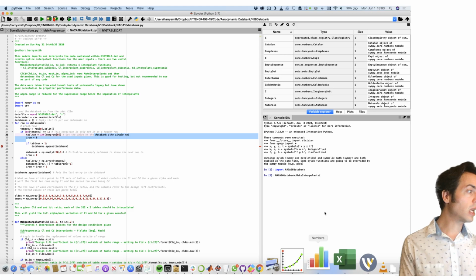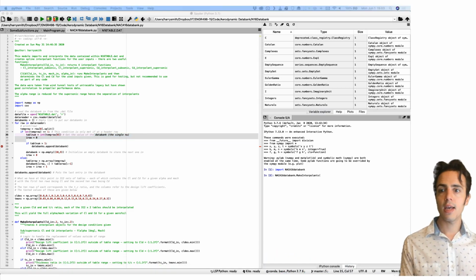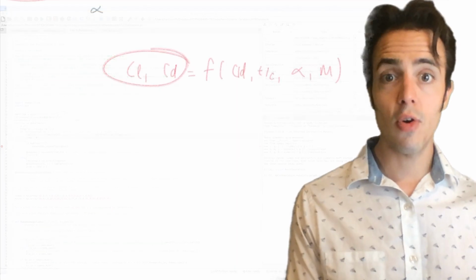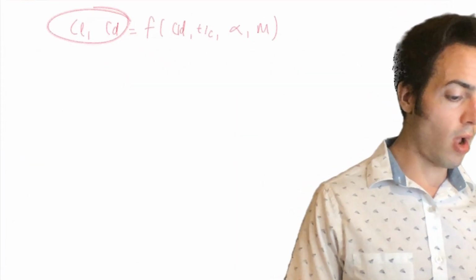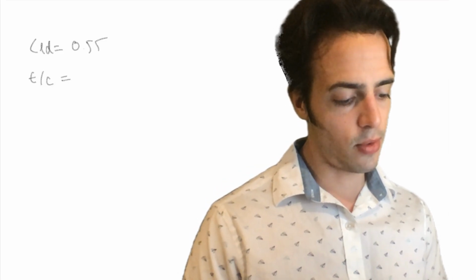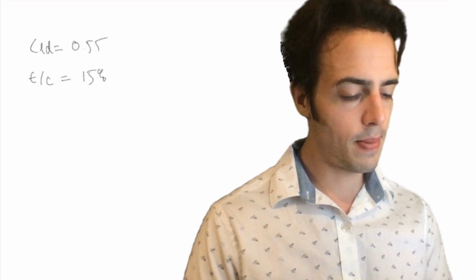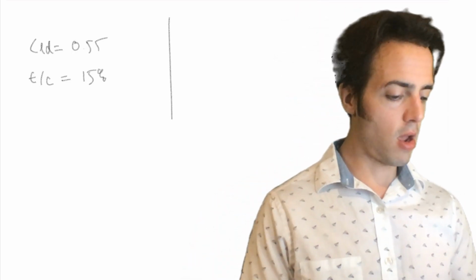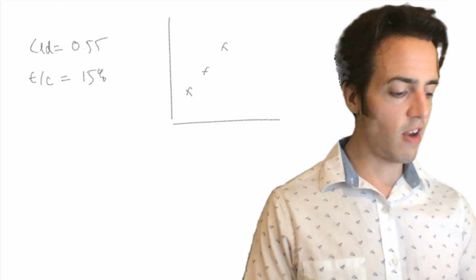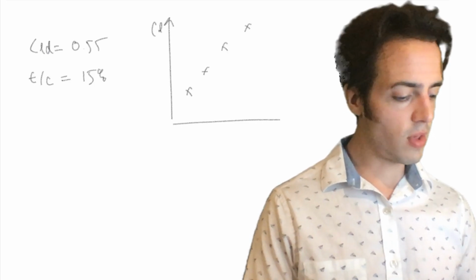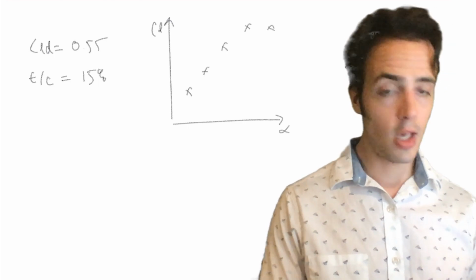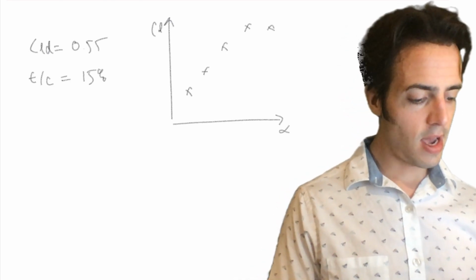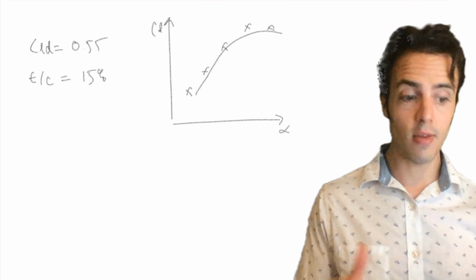And fundamentally what I would like to see is, can you compare how our airfoils work. I want you to say, okay, I've picked out an aerofoil from the Stack paper. CLD is equal to 0.55, TC is equal to 15%. Take those data out and I say, okay, I've got some experimental data that I've picked out for CL versus alpha. I've picked those out using ENGauge Digitizer, and I've then got my data. This is what the Databank says.